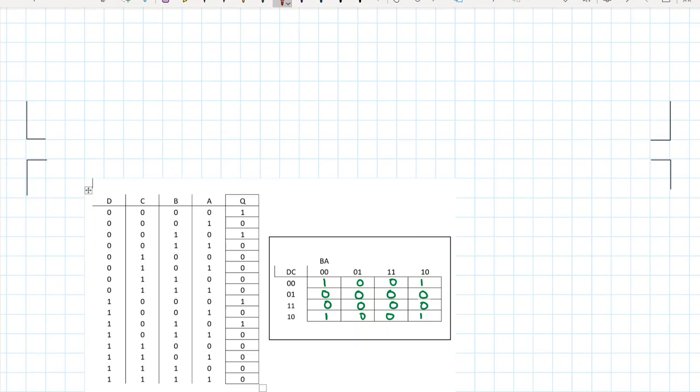One of my favourite ones is what can we do with this? So we're grouping in the largest group size possible. Well, actually with our Karnaugh map it wraps around top and bottom and left and right. So what we can actually do is loop it round there, and there.